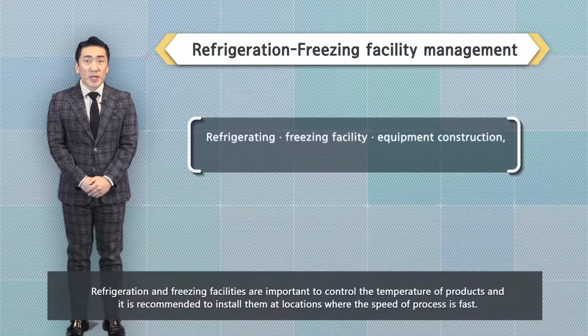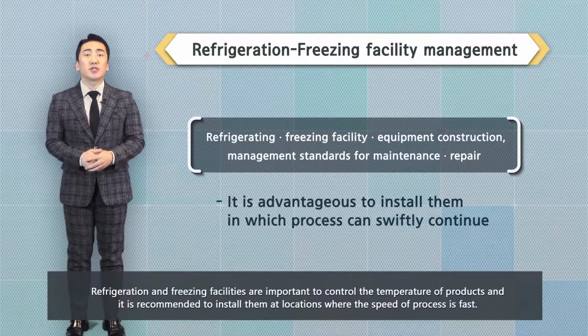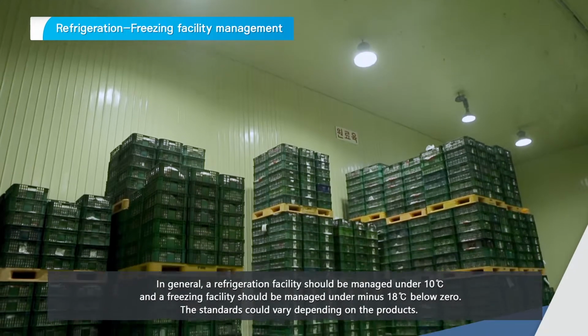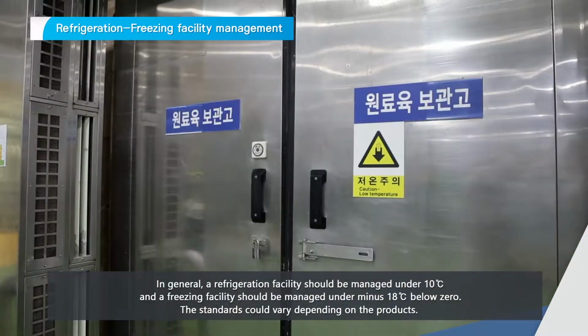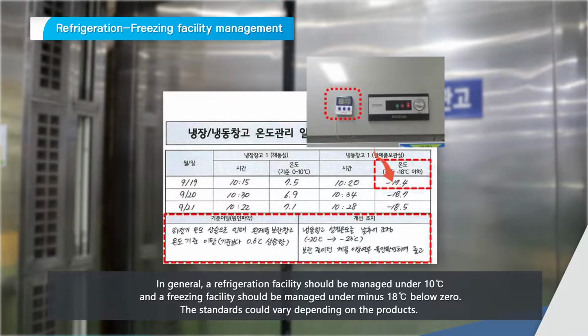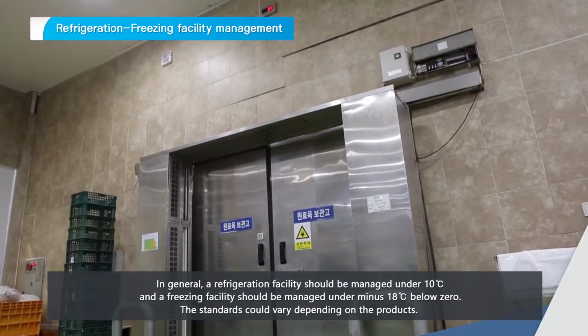Refrigeration and freezing facilities are important to control the temperature of products, and it is recommended to install them at locations where the speed of process is fast. In general, a refrigeration facility should be managed under 10 degrees Celsius, and a freezing facility should be managed under -18 degrees Celsius below zero. The standards could vary depending on the products.